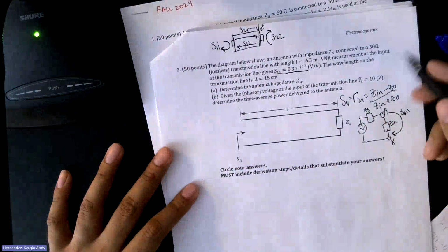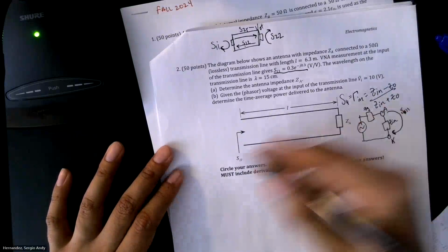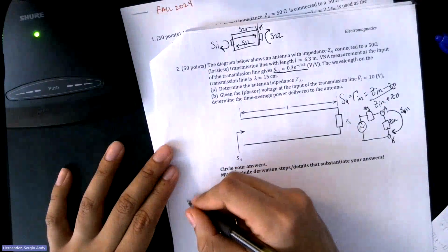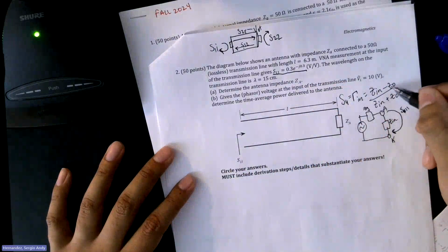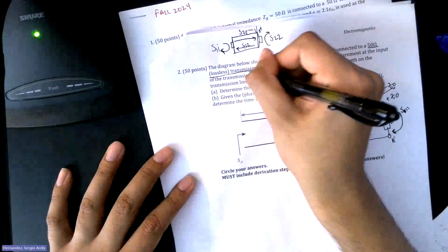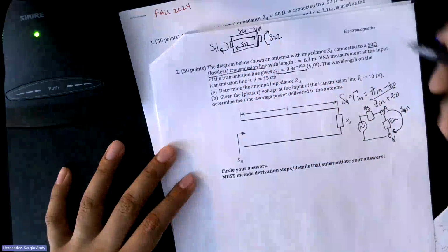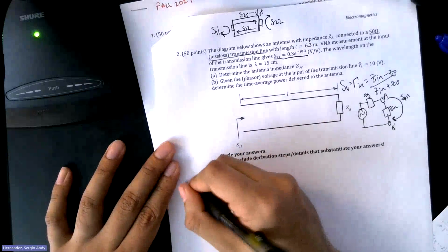So you just want to start off with this point immediately, right? So he gives you S11 here in the problem. He gives you Z naught also, connected to a 50 ohm lossless transmission line. So you're able to get